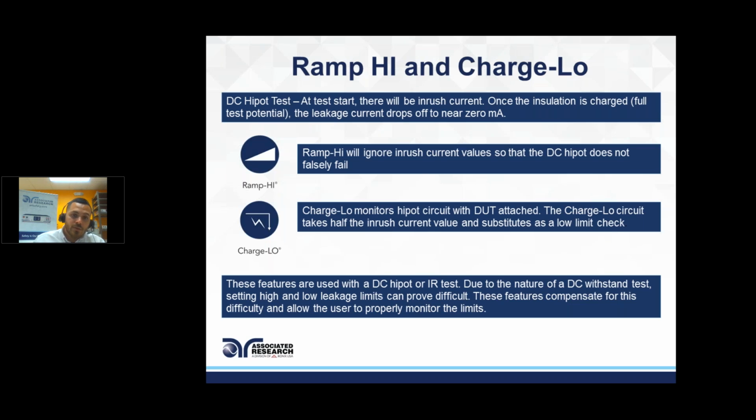That's great. So I convert my voltage from the 1.24K, multiplying by 1.414, or the square root of 2, pretty much the way to find your equivalent DC voltage from AC. I set that as my new test voltage for DC. I hit test and I'm still failing. Why am I still failing?